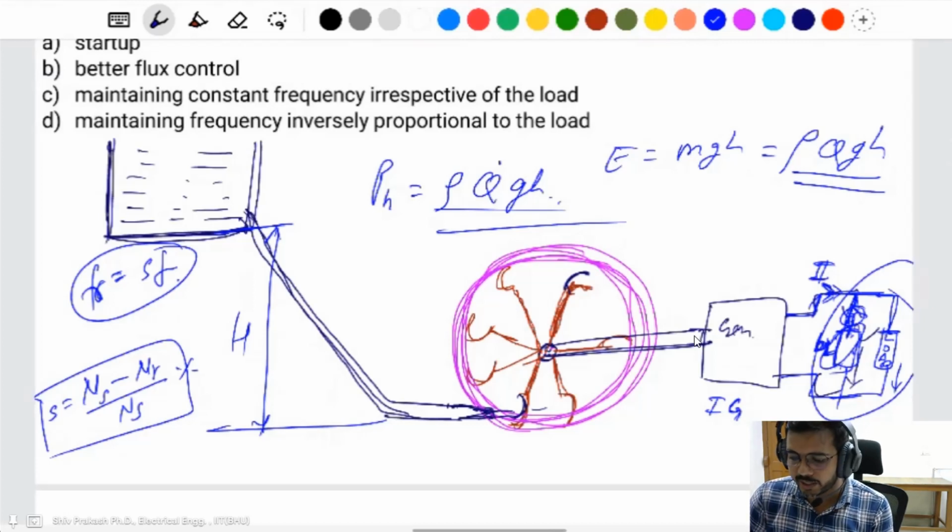If the ballast load is not connected to regulate the frequency, then there are changes in frequency because it depends on the load only. Also, because of the ballast load there are some losses. That's why the induction generator is not connected directly to the load. It is connected through a DC-DC converter to convert the energy into DC. After that, we connect it to the inverter.